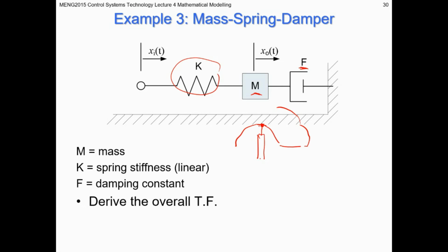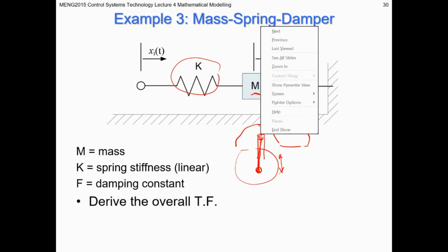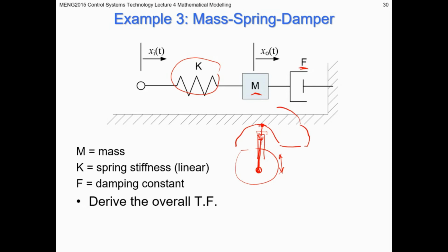And then the other end is connected through this shock absorber to the wheel, right? So you also have a spring around this as well. So this is actually a mass spring system. But just looking at the damper, it's filled with fluid, so that as the wheel moves up and down, there's a tiny little hole at the top of the shock absorber that allows the fluid to be compressed into a chamber.